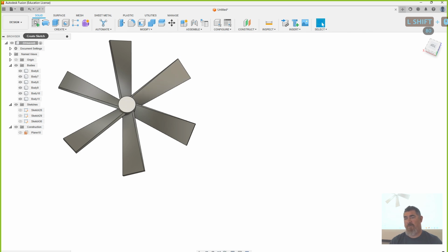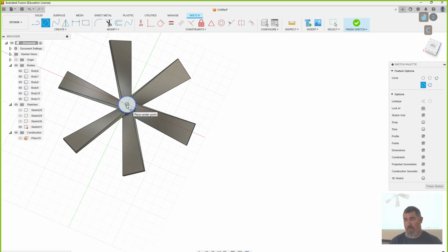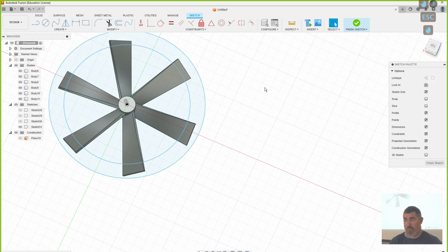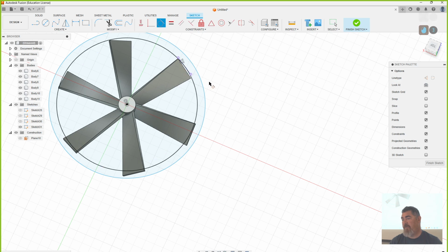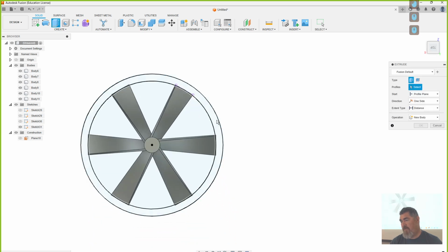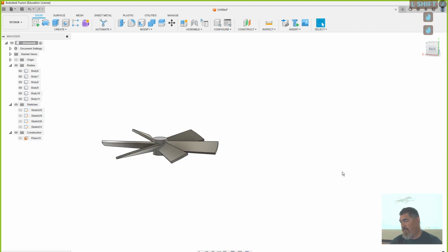And I don't want the sharp corners out there, so draw a circle up here. Draw a circle from there, out past it, then there, then project that edge. So let's do tangent. Cut that all the way down.